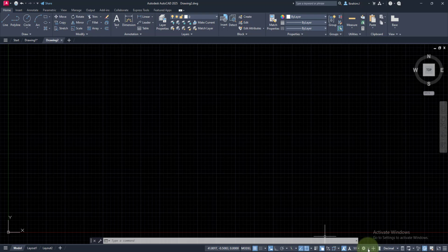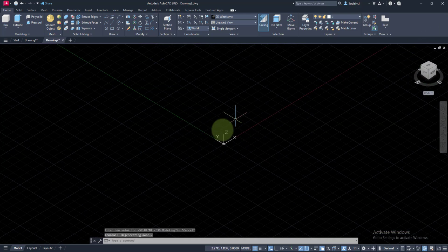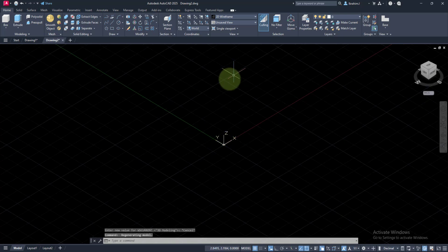So I'll go ahead and do the big boy stuff now. I'll select this and go to the 3D modeling workspace. Right there, on the 3D workspace, I still have my crosshair acting as usual. So I'll go ahead and click on home view. Now I have the big boy here. Now you can see that my crosshair has changed. It was showing X and Y before, but now it has changed to X, Y, and Z. And we know what Z is on our 3D workspace. Z can be our height or can be our depth for any other element that we put into our 3D.